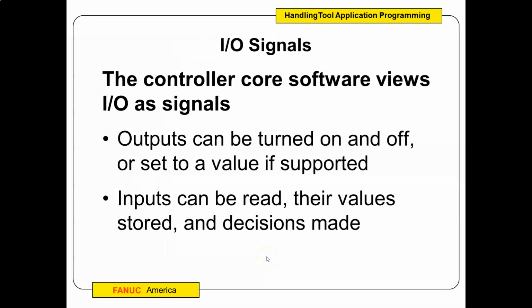And again, these I/O signals you can turn on, you can turn off, you can set to a value, if supported. Digital I/O is usually on and off. We'll talk about that. Other things, analog and group, you can set to a number. Again, inputs, you can read them, their values stored and decisions made. When we talked about if statements, we talked about I/O,